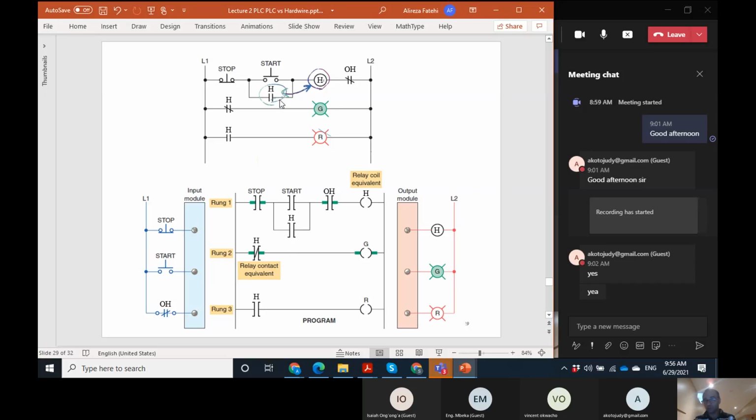This is a normal contactor, a typical contactor, not a latching relay or latching contactor, but we use this to latch. Exactly the concept that we're looking for. Right. It is also called seal in. Yeah, seal in or latch contact. Okay, that's very perfect. All right.